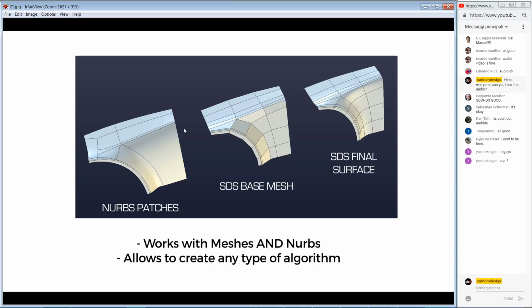Meshes have some problems when you want to manufacture products, because even if you can create a subdivision mesh which looks very good, you don't have control over the exact dimensional accuracy, the tolerances, or aesthetic qualities like curvature. Also, creating hard surface models using the subdivision surface approach is really tricky, because you have to take into consideration the topology and many different things.